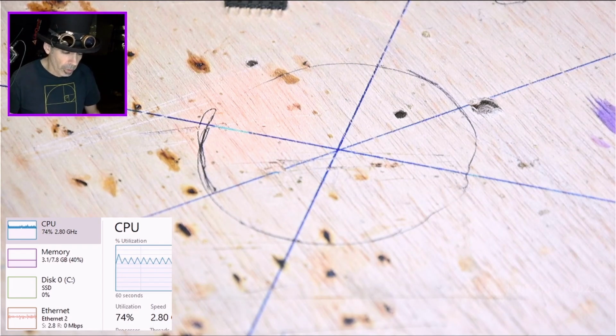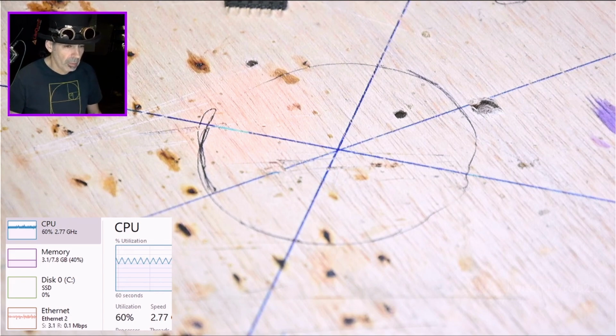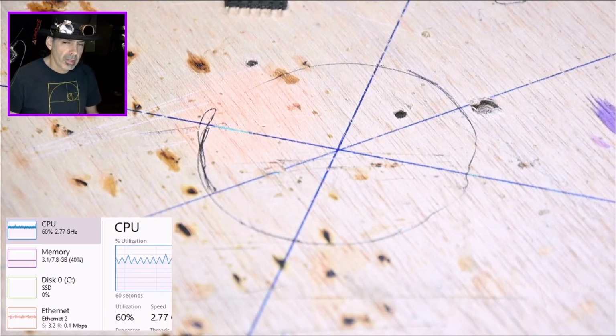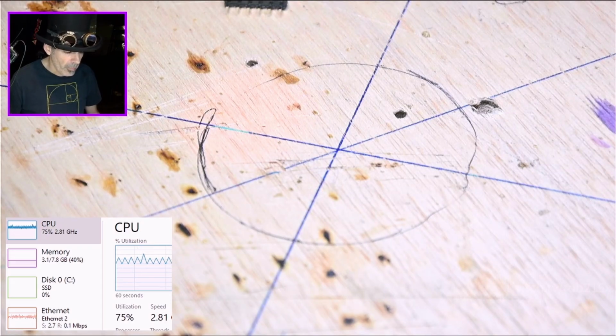One of the things about building drones is they need to be light. They need to be as light as possible because they'll fly longer. The lighter you make your drone, the more efficient it can be as far as staying in the air. And also, everything you do with power needs to be super efficient. So I've been using voltage regulators that are typically 95 to 99% efficient, meaning they don't waste power converting one voltage to another.